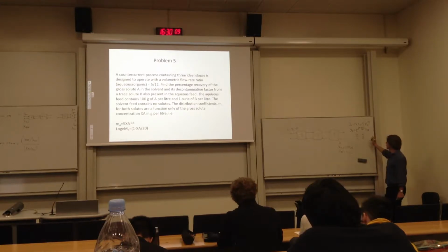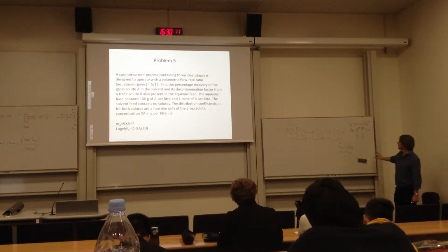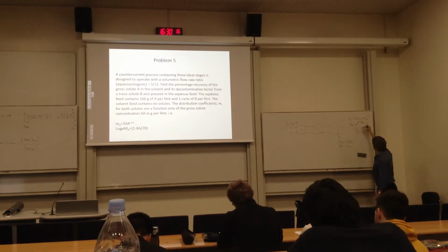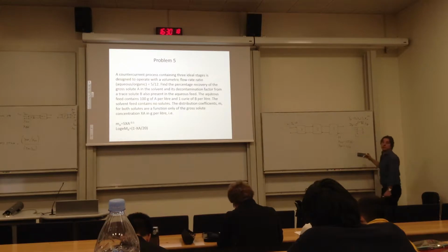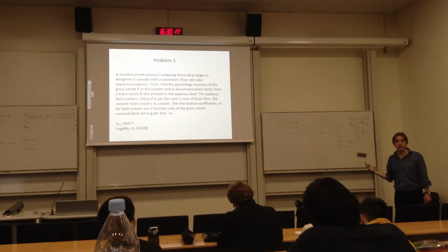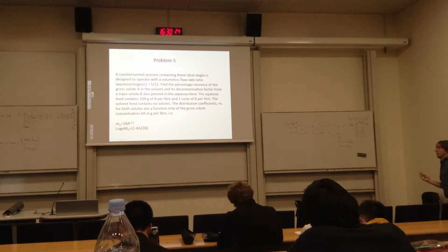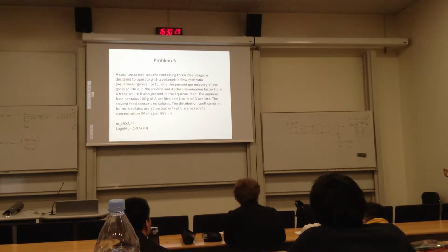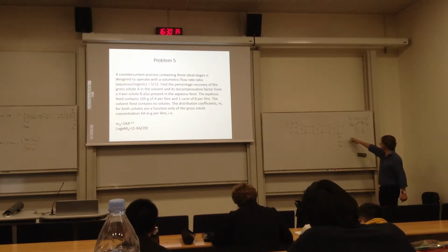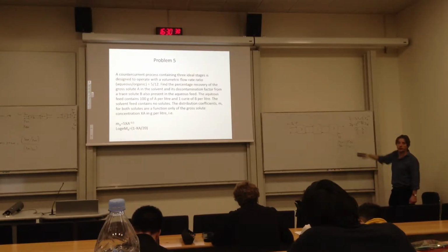Right? So let's look at this problem. H over L will be related to our operating line. It will be the slope of the operating line. Is the operating line the same for both? Yes. A and B have the same operating slope because they are in the same solutions and in contact with the same solvent, so this is the same problem.